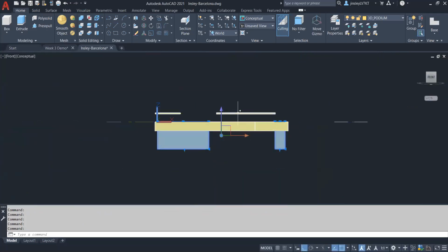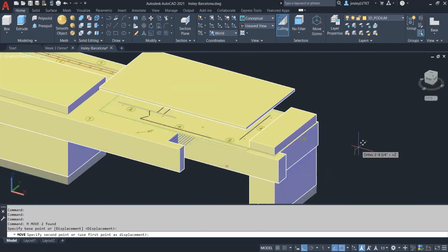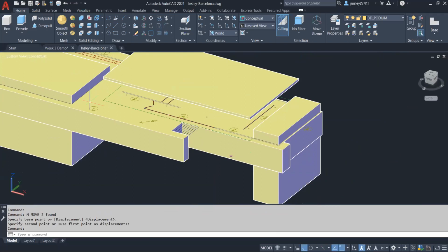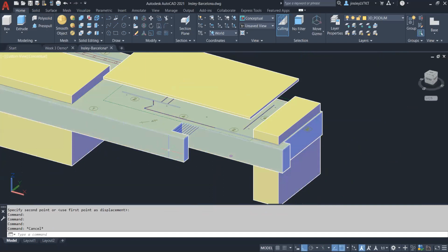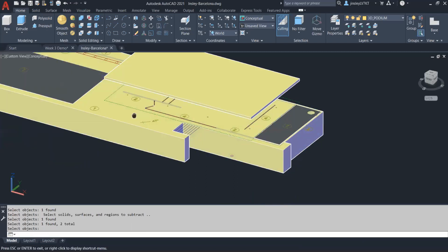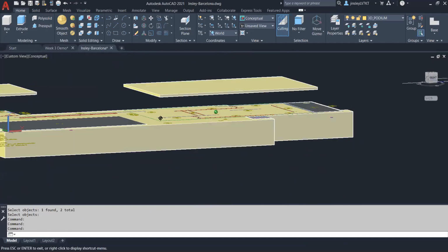It's dangerous to do that. You can create some really messy geometry. So I always grab them and go a little bit up so that I make sure that this subtraction object penetrates all the way through the solid. Now, when I subtract, I can pick my podium, I can pick the two objects to subtract, and I'll punch right through. Okay? You can see I've punched through on the bottom.